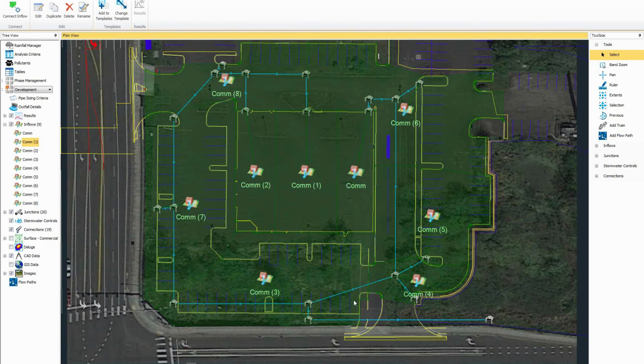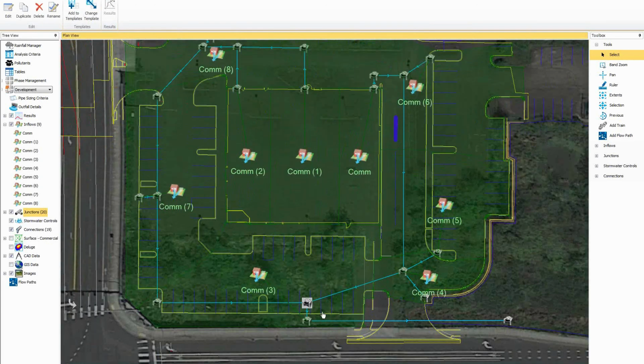Pipe networks and LandXML usually have to be oversimplified. Okay, so in the real world, what we need to do here is put an underground vault in this lower portion of our site. Well, if you're trying to make a pipe network in Civil 3D, there's no underground vault type of element for a pipe network.